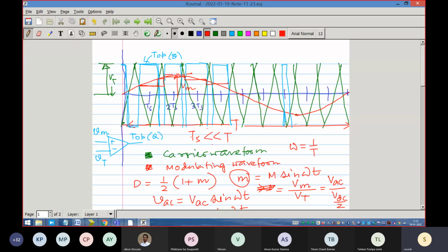I will tell you a little later, if I get time, when I talk about the frequency spectrum of this modulation. I will bring it a little more clearly, what is really done. The switching frequency is never allowed to vary beyond a certain value, and is never allowed to reduce beyond a certain value, right? So when we have to do a high frequency modulating signal, we reduce the resolution of our sampling waveform.